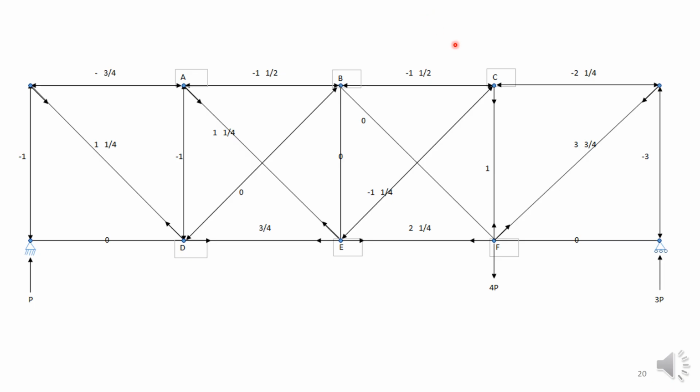So again, in structural analysis, what you often do is find a determinate substructure first, which is sometimes called a primary structure, and then you apply the loads to that primary structure and you get the forces in the members.